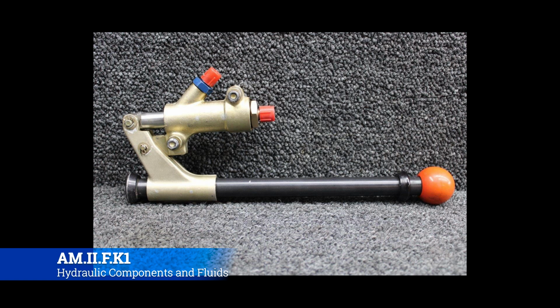The main thing that you have to bring to the table is just calories. You're going to end up having to hand pump that thing for a hot minute to get the landing gear to come down. Now these are often used as backups. Like we have one on the Aztec that you'll pump whenever we do gear swings. So just know that is a way to increase the hydraulic pressure in a system. There are other types of hand pumps that you'll see on some of the heavy commercial aircraft as backups for ground use, but you're not going to see anybody hand pumping down a 737's gear by any stretch of the imagination.